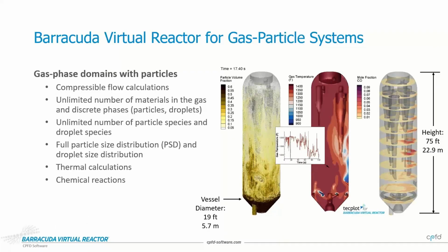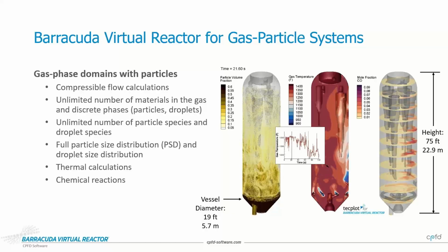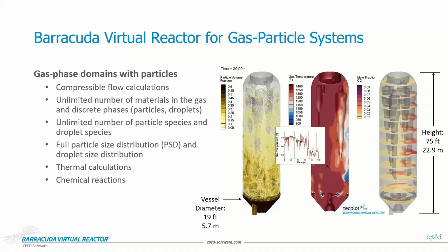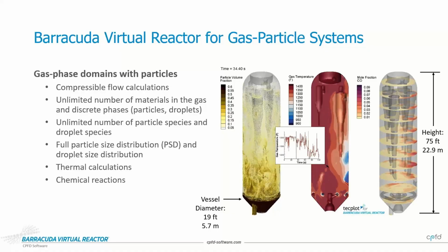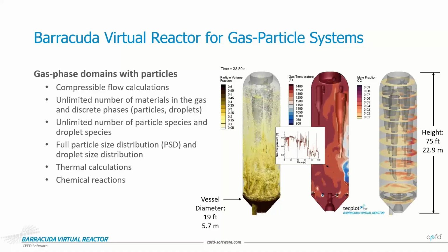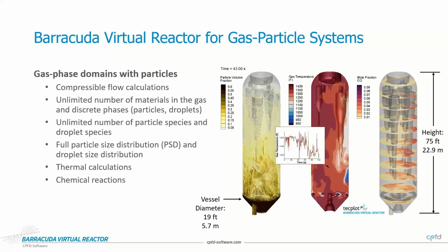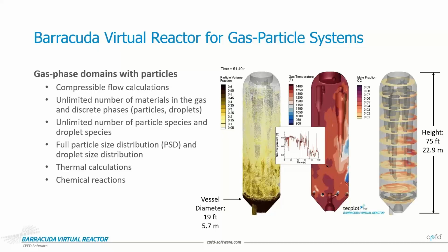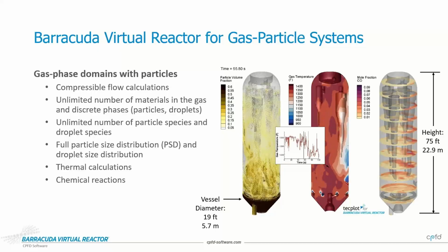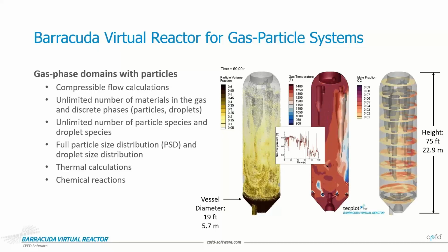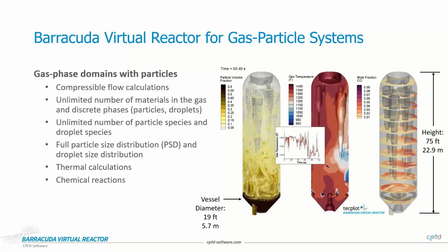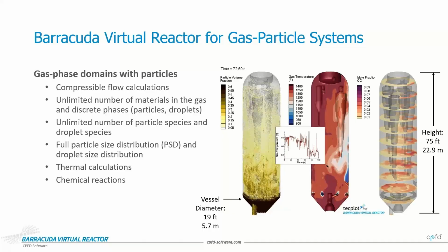Barracuda is divided into two broad domains, gas fluid domain and liquid fluid domain. The first broad domain of the software is gas fluid domain. So Barracuda simulates bidirectionally coupled particle physics and fluid dynamics. The particles displace the fluid and the fluid acts on the particles via drag. And additionally, Barracuda models truly multi-phase heat transfer and multi-phase chemistry, where solids and fluids can both be created and destroyed through reactions.